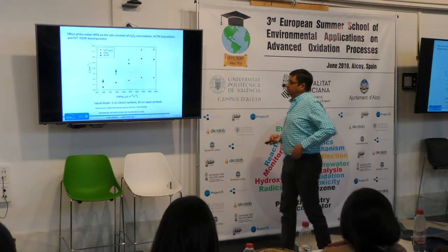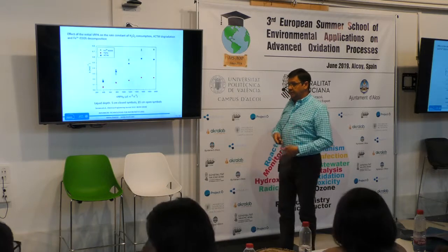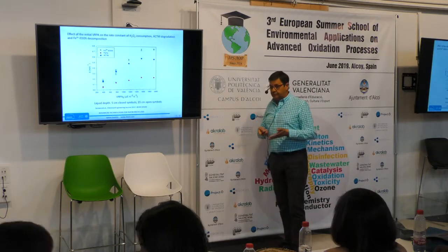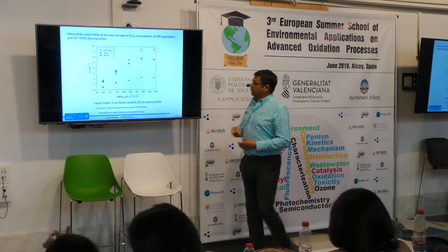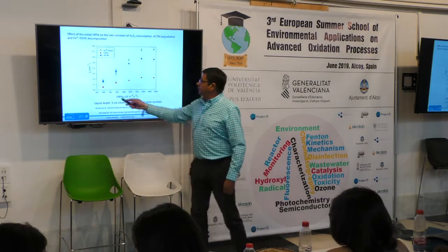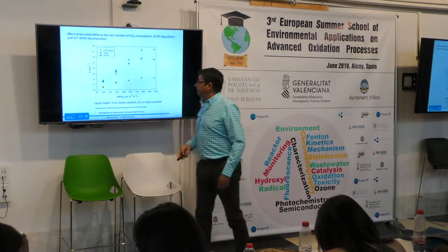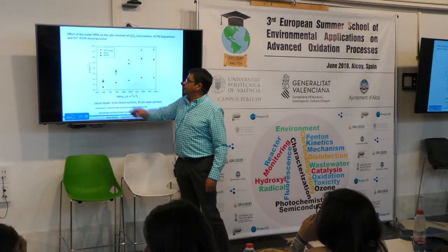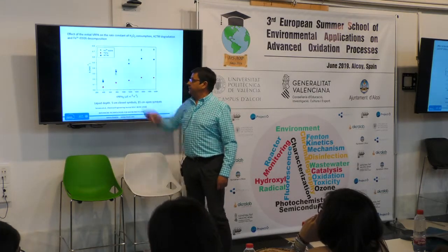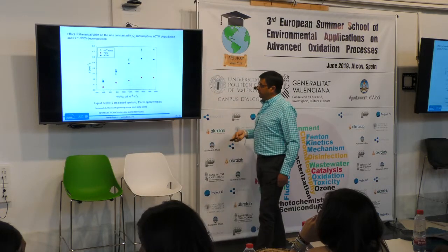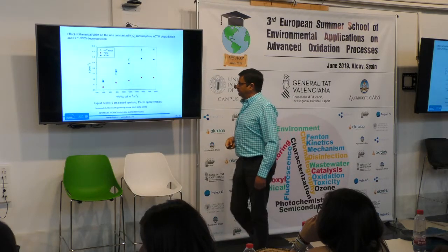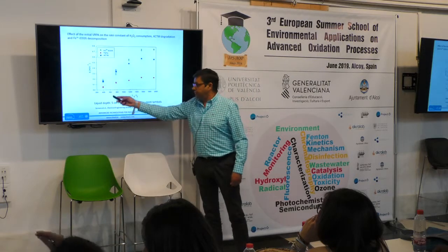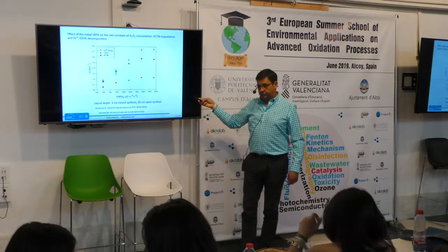So this phenomenon should be taken into account in the modeling process. In this figure, the effect of limitation or saturation is best observed, representing the first order rate constant for the decomposition of the complex, the consumption of hydrogen peroxide, and the degradation of acetamiprid, as a function of the volumetric rate of photon absorption.